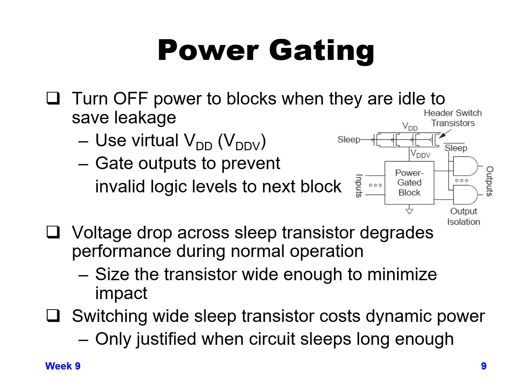You basically want to provide your voltage supply with virtually no voltage drop across your transistors. So you need a lot of them in parallel in order to send the output of this parallel bank of transistors to a block of logic.